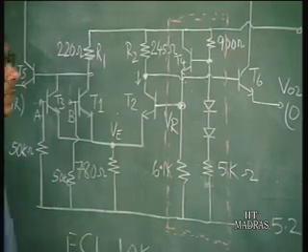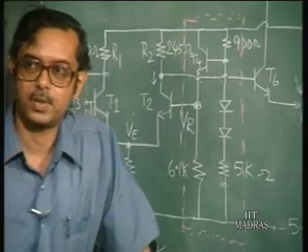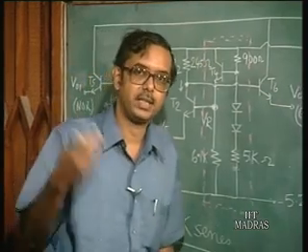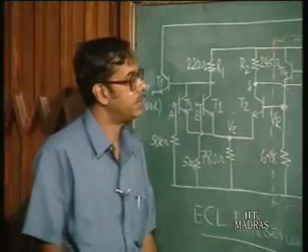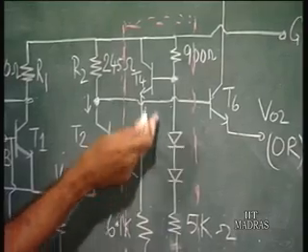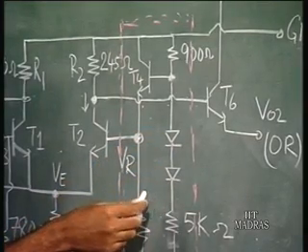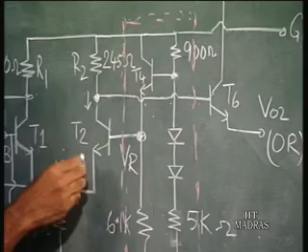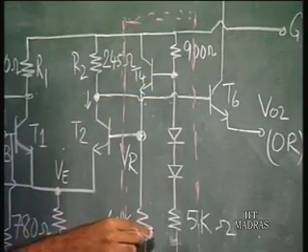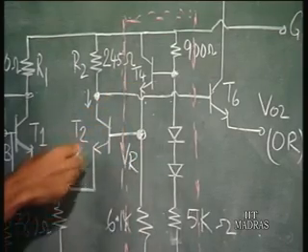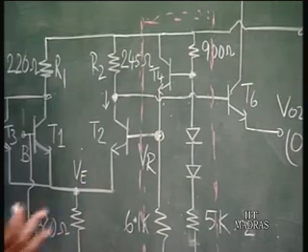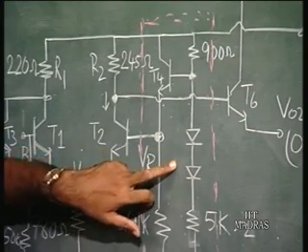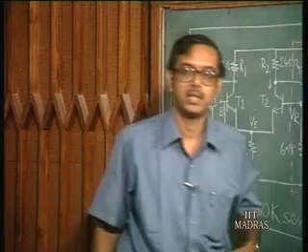Correct. You know that the base emitter voltage of a transistor changes around 2 millivolts per degree centigrade, and when you convert that to current, because of the exponential nature, you have a lot of difference. So, when the temperature goes up, the voltage across these diodes also changes. From this point, you have 2 diodes here, and these are the 2 base emitter voltages here. The presence of these diodes actually compensates for any change in the voltages across the base emitter of these transistors. So, you do not have any problems as such. So, these diodes are used for temperature compensation. Otherwise you could have had a simple potential divider type of network.